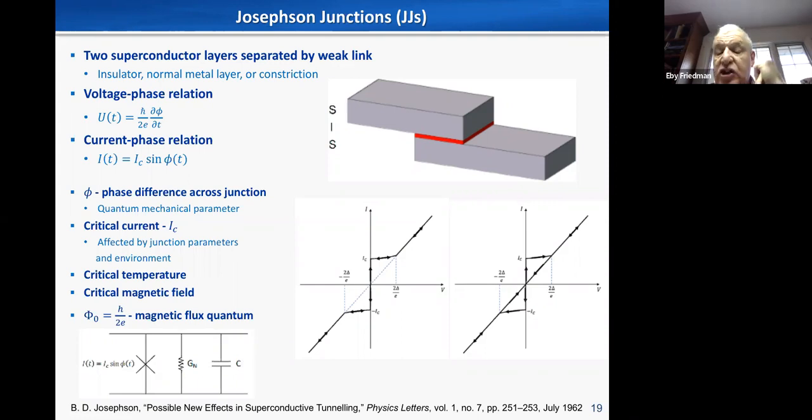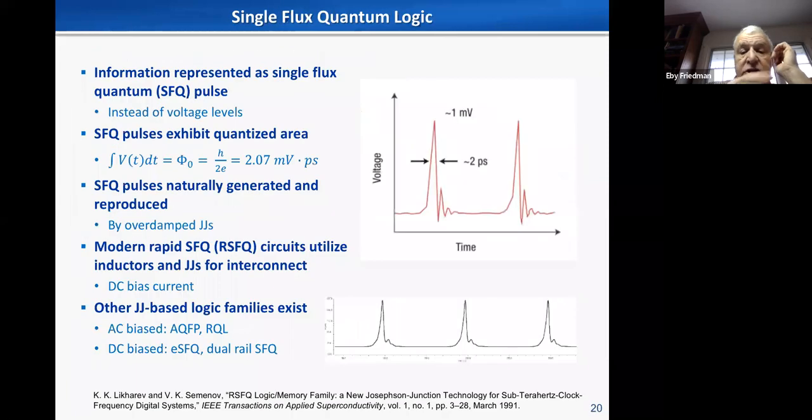And so the trick is to switch it between superconductive and normal behavior, and it produces this interesting quantum flux, which is expressed by this expression, h over 2e. This is the classic expression for the quantum flux, and basically the design of these circuits is the process of pushing around these quantum flux from gate to gate to gate, and we do it in a way shown here.